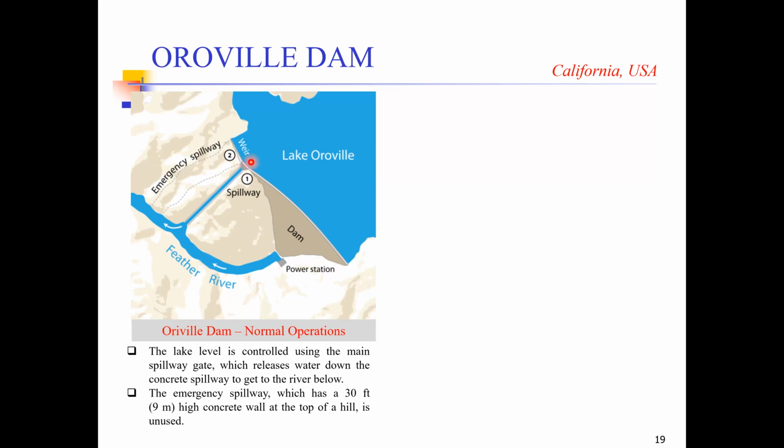Now, this spillway was used when the power station had to be turned off, when the water cannot go out from here, or when there are any repairs going on, or maybe there is a high flood coming from the back end. The extra water would be drained out through this spillway. Besides this main spillway, there was a location for an emergency spillway over there as well.